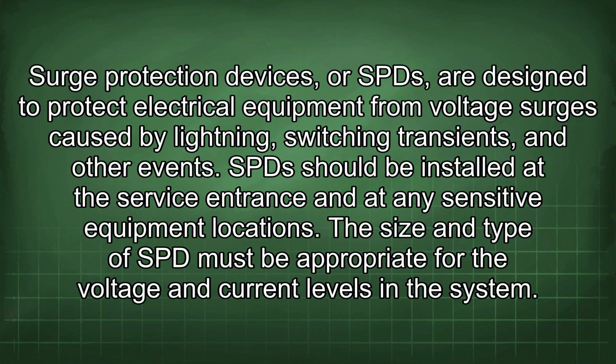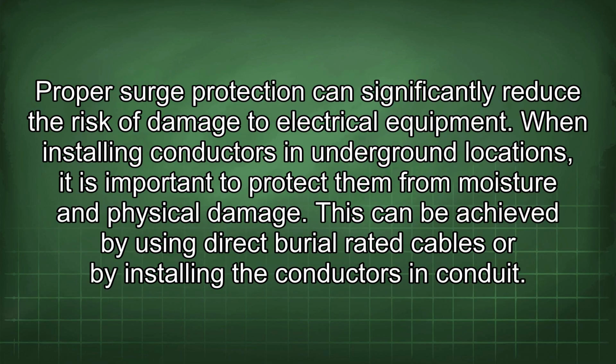Surge protection devices, or SPDs, are designed to protect electrical equipment from voltage surges caused by lightning, switching transients, and other events. SPDs should be installed at the service entrance and at any sensitive equipment locations. The size and type of SPD must be appropriate for the voltage and current levels in the system. Proper surge protection can significantly reduce the risk of damage to electrical equipment.